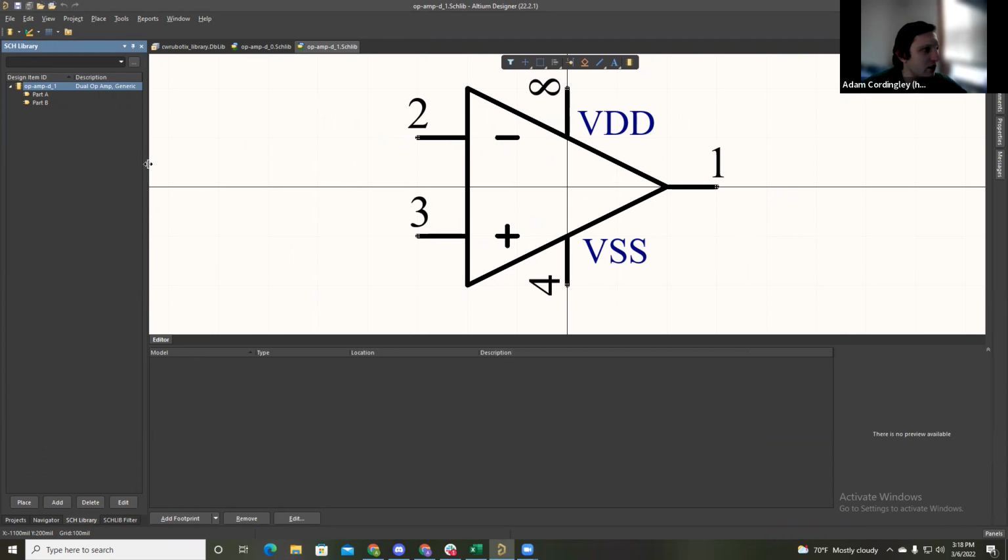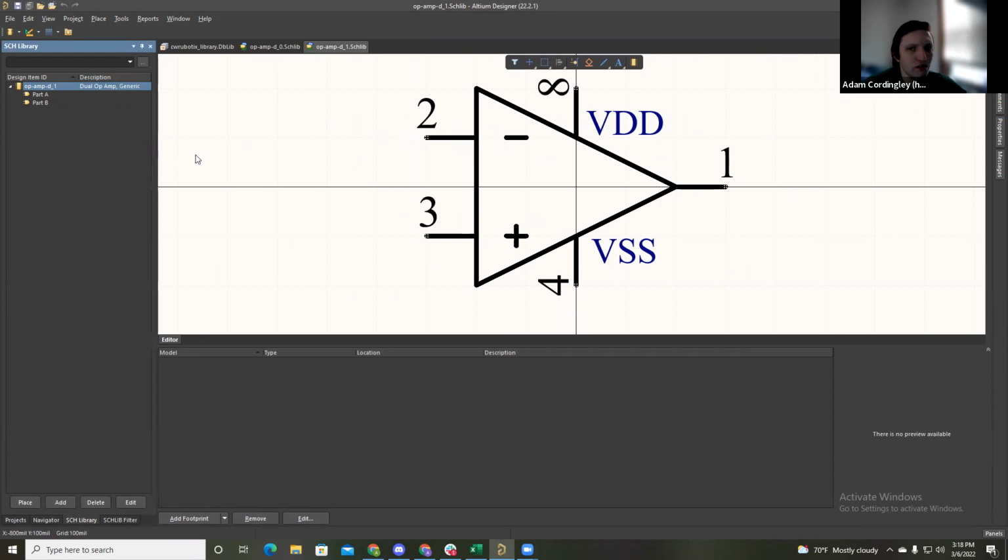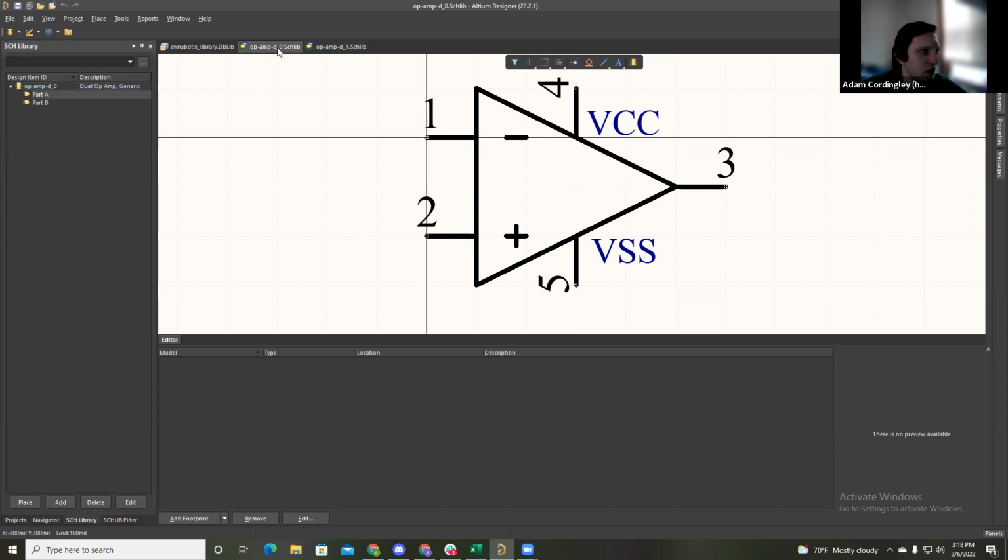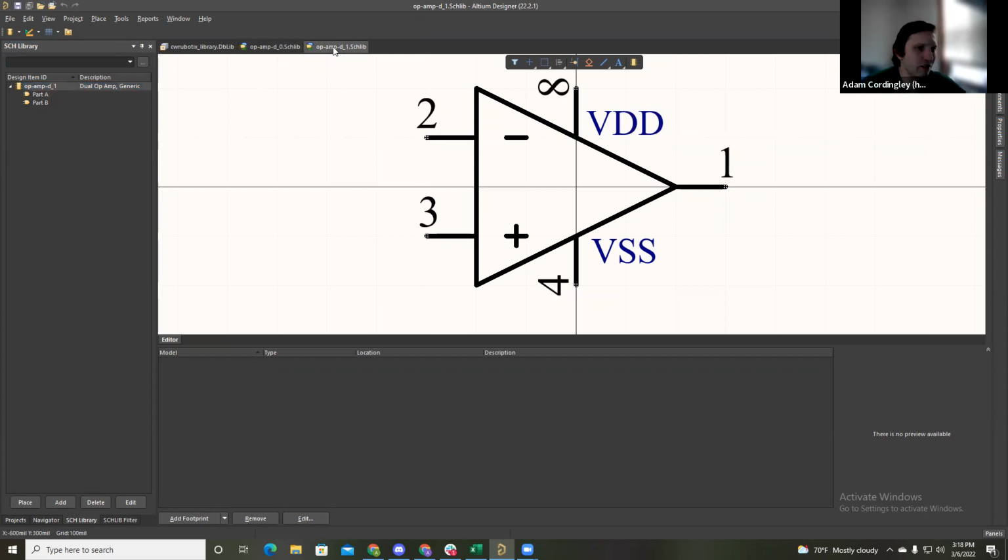The reason we've chosen to do it this way is purely for ease of version control. Because every schematic lib file is a binary file, if you made a change to a single symbol, it has to change for Git to understand the binary. It has to basically change the whole file. Whereas if you want to change just one symbol, it would be nice to change only one file of many. That's the basic reason why we've chosen to do this. It doesn't really change anything except that you end up with a whole bunch of discrete files.